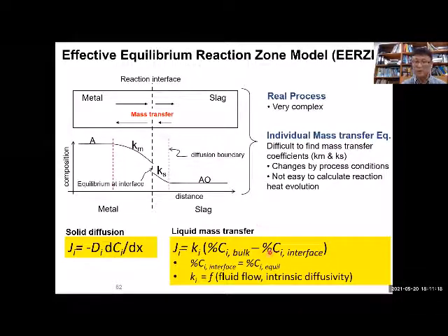But if you have a liquid phase, for example coffee with milk, if you stir the milk and coffee with your straw very fast, then it can mix much more quickly. So in the liquid state, the diffusion is not just diffusion by the atom itself; by increasing the stirring energy, you can accelerate the mixing. So in the liquid state, we don't express diffusion in this way. We express flux as a so-called mass transfer coefficient times the concentration difference like this, okay?